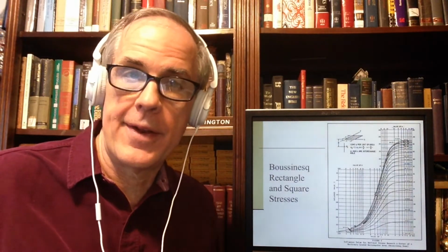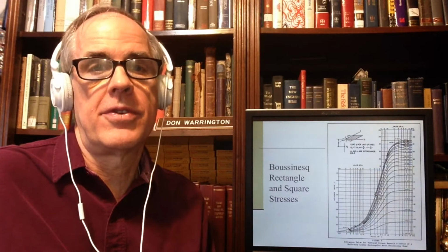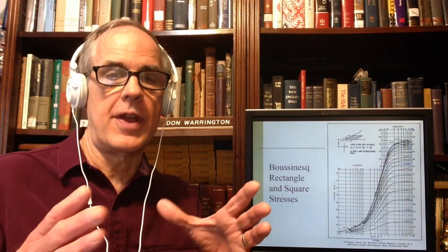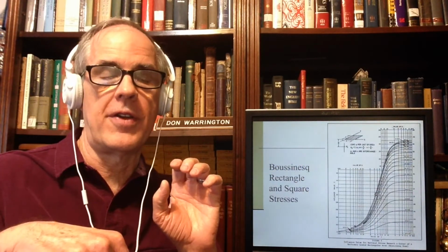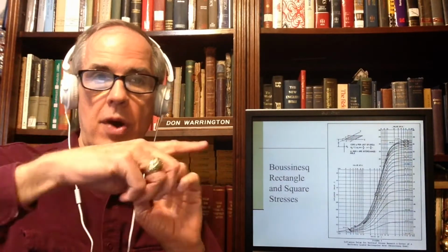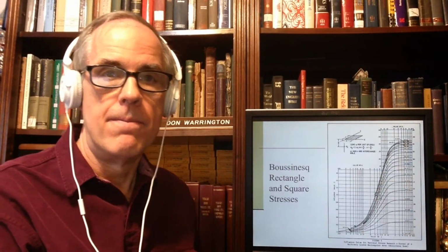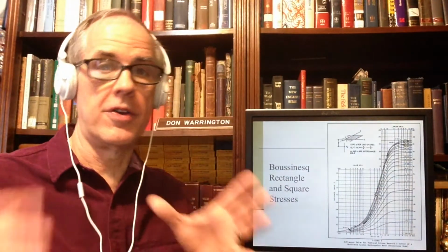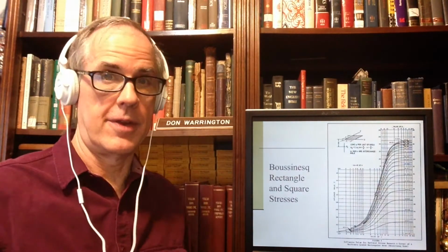The reason is that if you were dealing with a foundation and you want to do it at the center of the foundation, then each of the quadrants is only 1/4 of the load. You add them all up, you get unity. So for a very large foundation you approach that, and obviously a small foundation is going to be less than that.